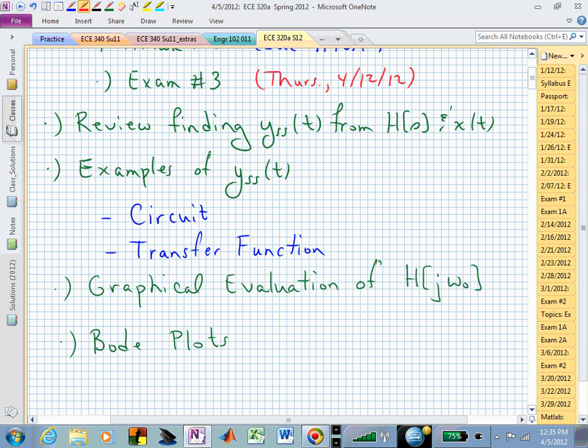which, if we got into Fourier series, you might have signals x that are composed of all sorts of sinusoids, and we might like to know, how is this system going to behave at 1 radian per second, at 2 radians per second, at 3 radians per second. So we march at J1, J2, J3, and we can tell how the system then will respond to each of those frequencies once we know this information. Yes? And you can do a superposition. The comment was, can you use superposition?